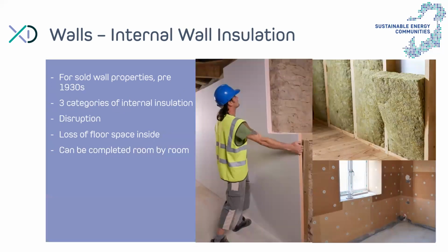Internal wall insulation is the next option, which deals with the same issue. You know, it's a solid wall typically. It's hard to insulate, and, you know, there's no cavity, obviously. So we're doing something quite similar effectively to external wall insulation, but we're placing a board of insulation inside, and then we're finishing it typically with a plasterboard.